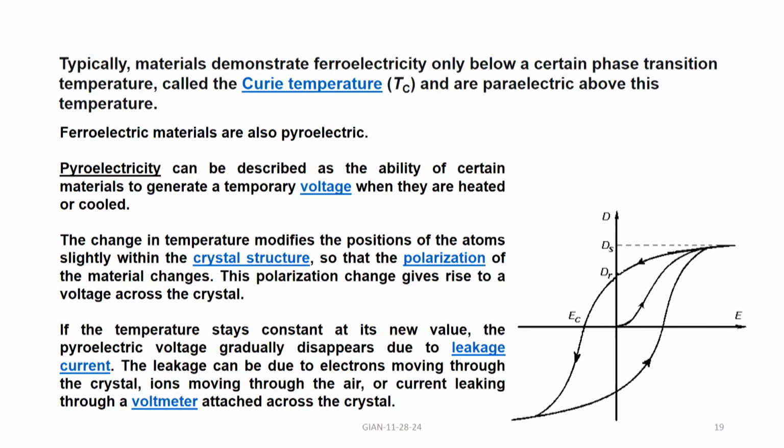So, you can polarize the ferroelectric, it's okay, but their resistivity is not infinite, it's finite. So, you have accumulation of charge, positive charge on one end, negative charge on the other end, when all the dipoles are oriented in a particular direction.